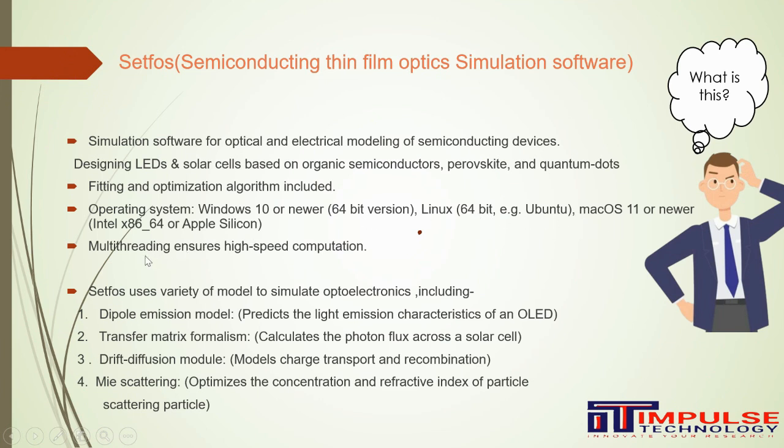Multi-threading ensures high-speed computations, so a number of processes occur at one time. Setfos uses a variety of models to simulate optoelectronics, including the dipole emission model, transfer matrix formalism, drift diffusion model, and Mie scattering. It optimizes the concentration and refractive index of scattering particles.